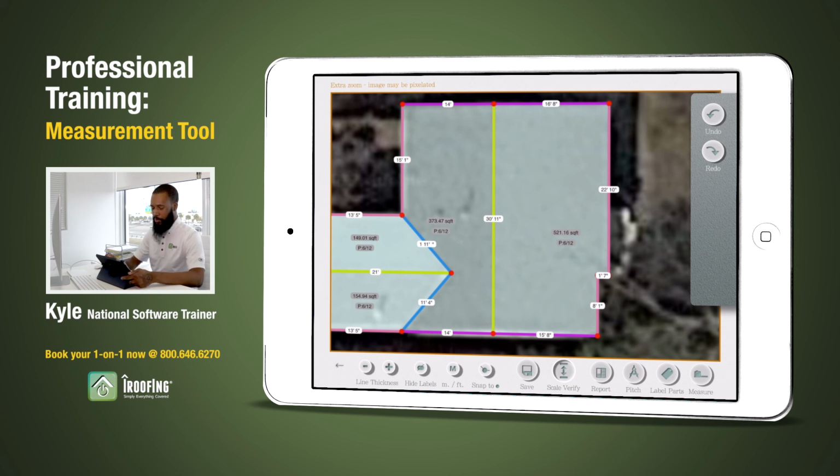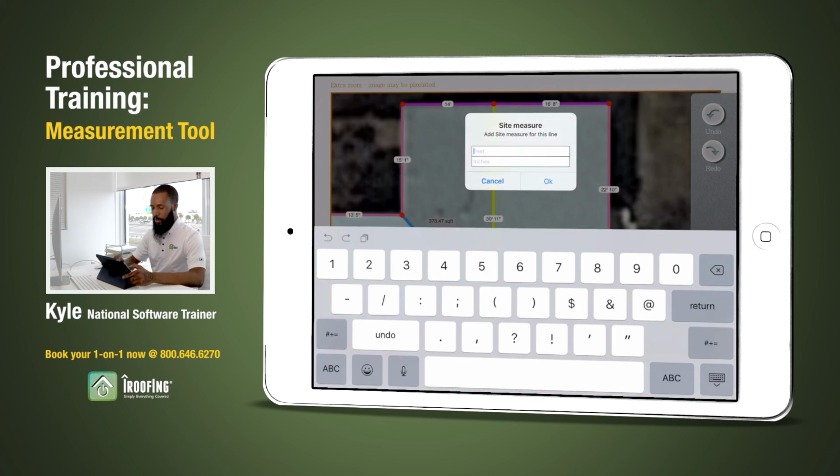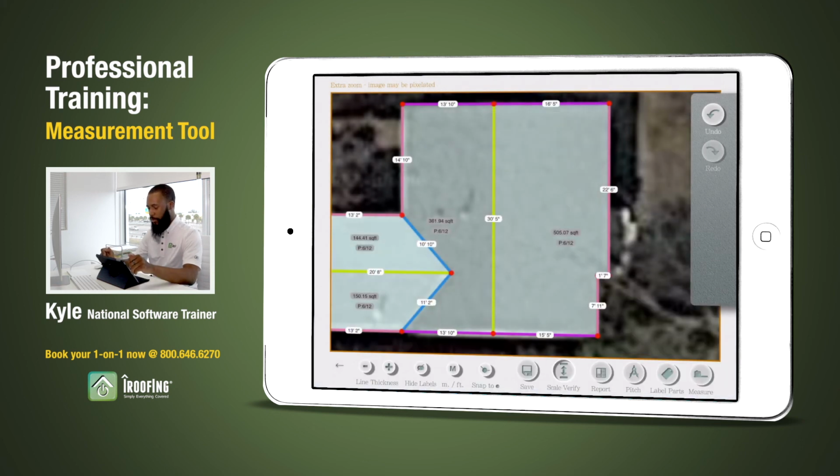So let's say, for example, that we went out to the job site and we realized that maybe we over-measured the roof a little bit. Maybe the eave along the front that I got 22 feet 10 inches on was actually 22 feet 6 inches. I can tap on that line after tapping on Scale Verify, type in the correct measurement of 22 feet 6 inches, and that's going to scale my picture down based off of that measurement. So this way, I make sure that I'm getting as close to accurate as possible with my numbers.